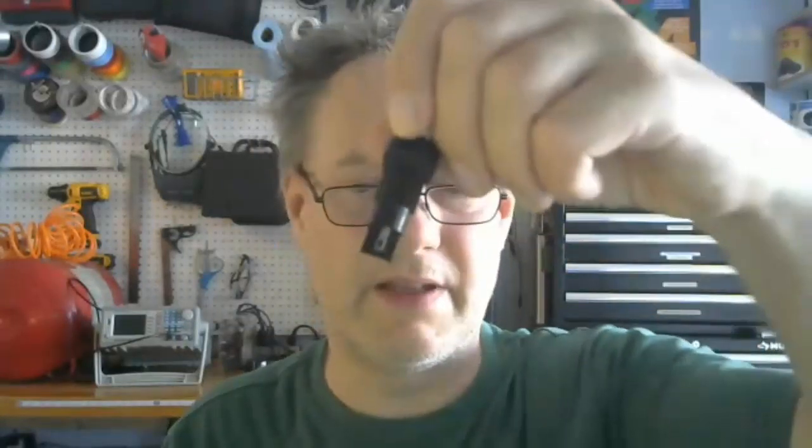Now, if I go even smaller, like these little guys, this little tiny thing is meant to be soldered onto a circuit board, and I wouldn't put more than a quarter amp through it. Sorry, this is my original one that I pulled out. Again, the leads are pretty small, so you can get a sense of how much current can go through a switch depending on how formidable it is. This thing is pretty tough, right? You can really feel it. It's a mechanical thing. So I'm going to put maybe 10 amps through that. But again, I'd probably want to look at the specifications. Ooh, there's a code on here. I might be able to Google that and look it up.